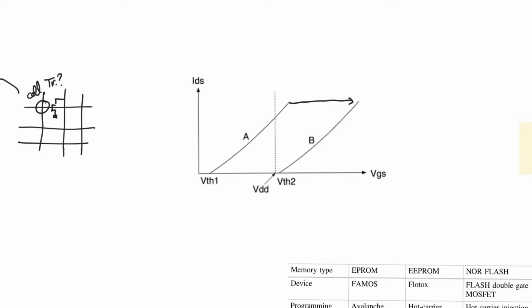So we can actually program the transistor to not exist, because its threshold voltage is so high that we will not be able to turn it on while operating. If the transistor characteristics can move back and forth between the two characteristics, then we have a non-volatile memory, because we can change the value written in the cell between 0 when the transistor doesn't exist and 1 when the transistor exists, if we are looking at a NOR ROM.